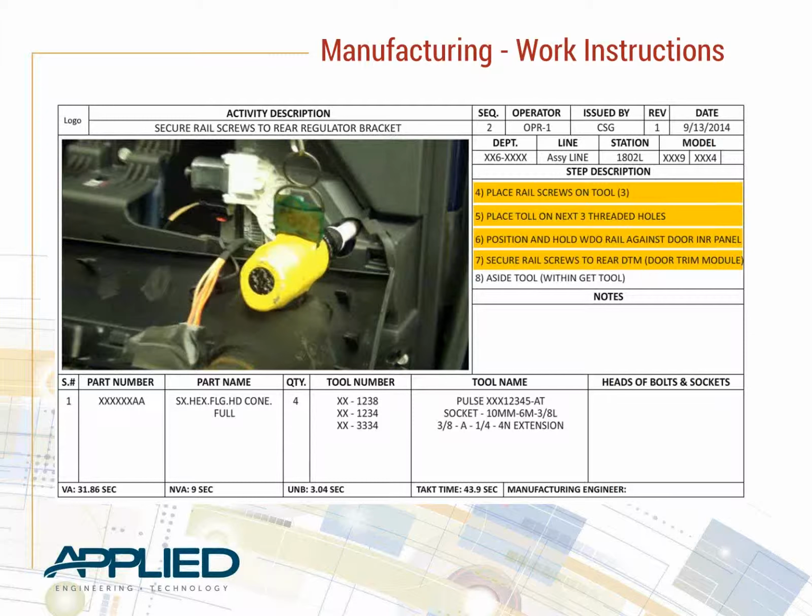So if you break it into a database form and break it down to its smallest components, and then rebuild it back up, each action up into a process, each process into a sequence, each sequence into a package of sequences into the workstation, and add up all the workstations, you can see how you can build back up all your times and take a really good, accurate look at it.